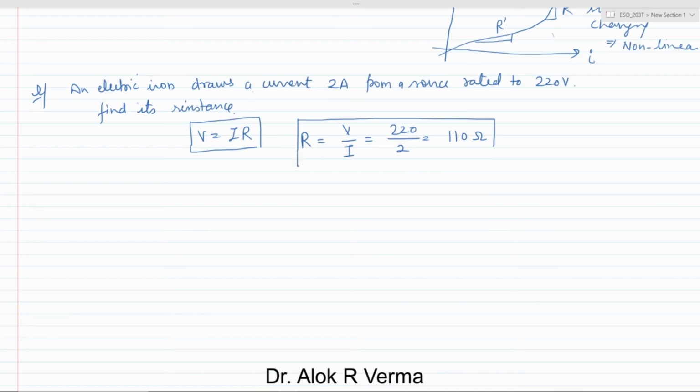We could find out using Ohm's law very easily, but the assumption is with temperature. Iron can go up to a very high temperature, but R is given, which is not a function of temperature, because we have not been provided the coefficient of temperature variation. So how much the dependency of resistance is happening on the temperature is not provided. So for that case, assuming R to be independent of temperature.